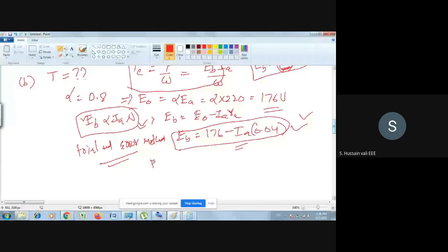Then in that case, you have another equation for EB. Yes, correct. That is also one possibility, that you go for this equation EB2 by EB1 is equal to IA2 N2 by IA1 N1. This is one method. Or we better find out the K here. EB is equal to K IA N. From the previous thing, we can find out the K value, and N value we know here. Then IA, EB, two unknowns, two variables, that's correct.